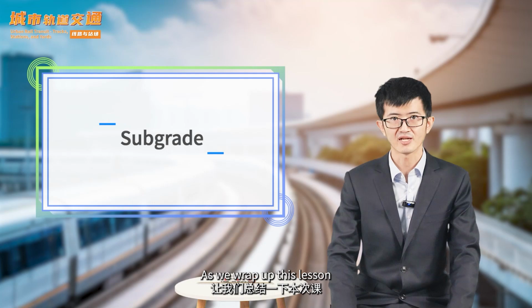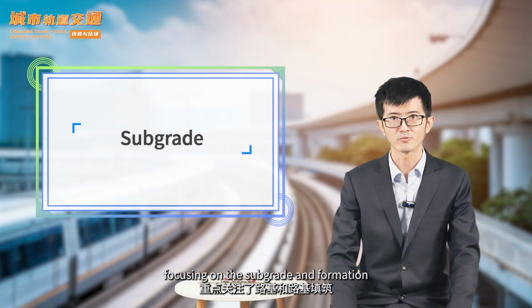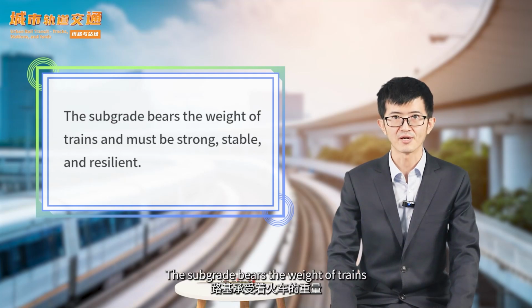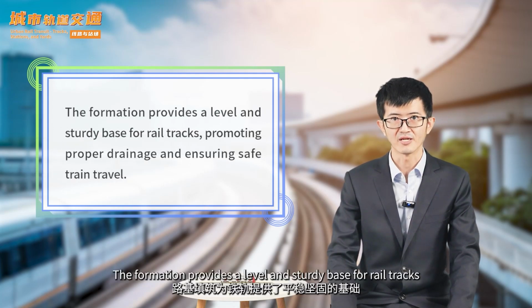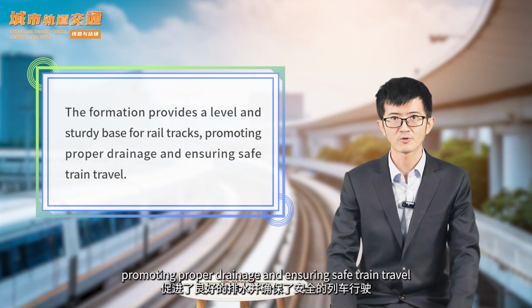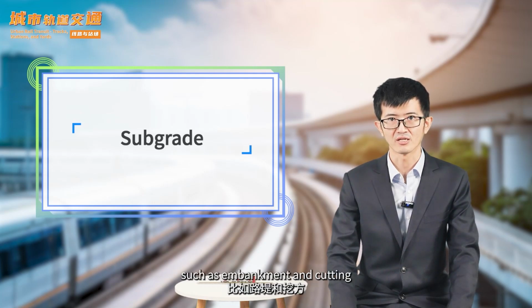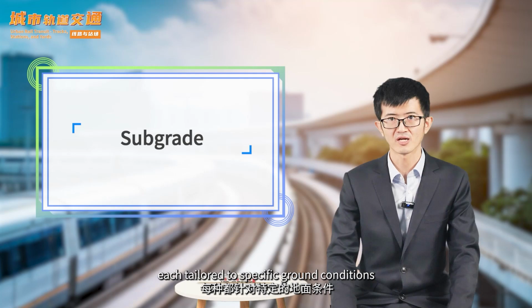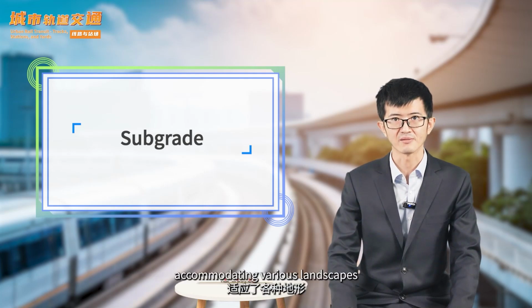As we wrap up this lesson, we covered the significance of railway track beds, focusing on the subgrade and formation. The subgrade bears the weight of the trains and must be strong, stable, and resilient. The formation provides a level and sturdy base for the rail tracks, promoting proper drainage and ensuring safe train travel. We explored 6 formation types, such as embankment and cutting, each tailored to specific ground conditions. These methods ensure a stable foundation for railway tracks, accommodating various landscapes.